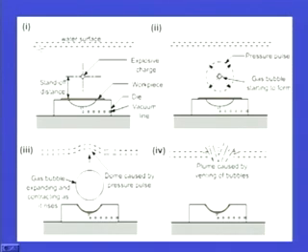See, this is the water surface plane here, then this is a dome that has been caused by the pressure pulse, and you can see that the pressure pulse has here deformed the sheet metal. Till the second stage, the deformation has not taken place, but a pressure pulse has been generated on detonation of the explosive. After this pressure pulse impinges against the sheet metal, it deforms the sheet metal like this. In the meanwhile, the gas bubble expands and contracts as it rises.